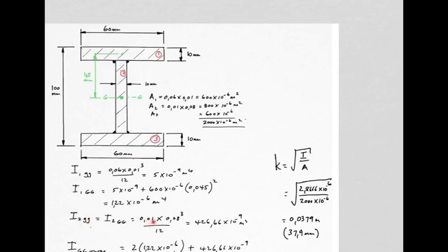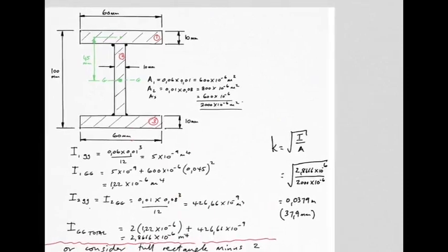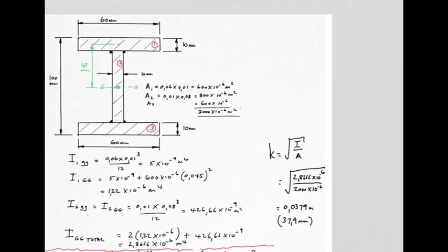So once again, B, which is this way, remember, parallel to the axis, which is the 10 millimeters converted to meters, times 0.08, that's this one, perpendicular to the axis in question, 80 millimeters converted to meters, 0.08, it's the one that gets cubed, remember, over 12, and there you have the answer. So now GG total for everything is going to be one of those for this one,